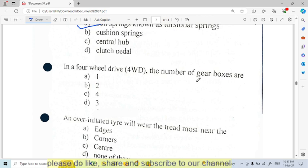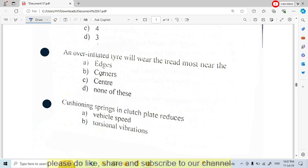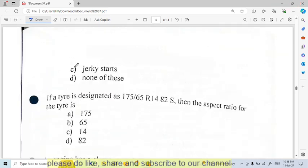In a four-wheel drive, the number of gearboxes will be 2. An over-inflated tire will wear the tread most near the center. Okay. So an over-inflated tire, that means excess tire pressure, will wear the tread most near the center. The center portion will be damaged. Next, the cushioning spring in a clutch plate reduces jerk at start.